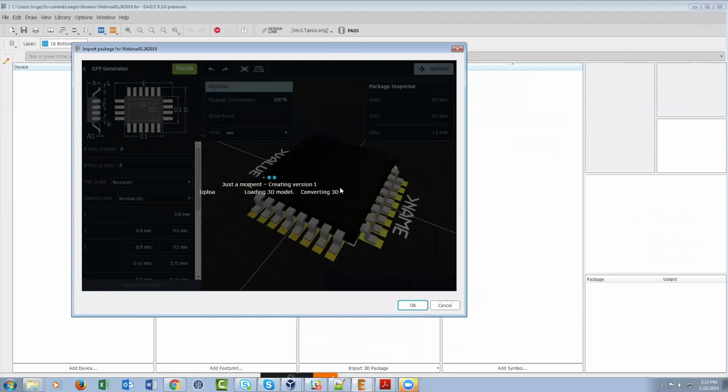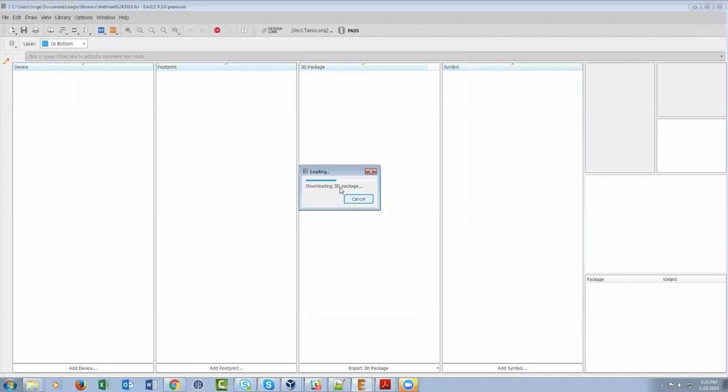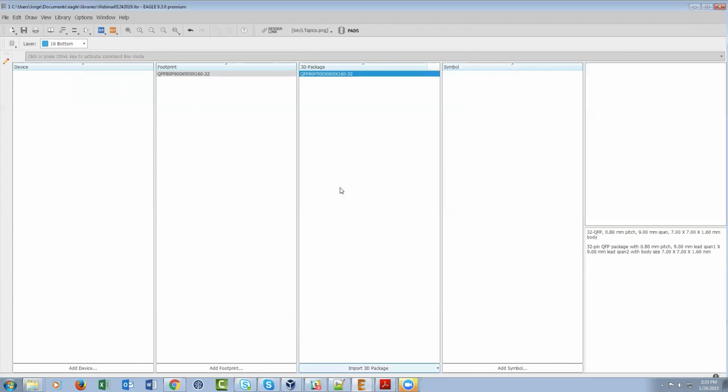Now, in newer versions of Eagle, there's very little reason to go to library.io these days. You can pretty much do everything from within Eagle. So that makes it a lot easier. You don't have to go and open up your web browser and go to library.io. Library.io is still useful if you want to clean up, if you want to destroy libraries that you don't need anymore and stuff like that. But most of the workflow can actually be done from within Eagle, and that's what we recommend nowadays. So yeah, you could actually clean up from the control panel now. Your managed library. I was testing that the other day.